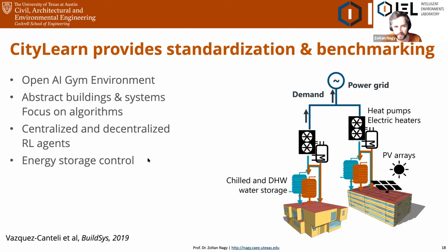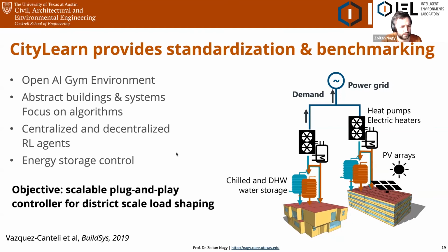All the buildings will maintain their thermal set points. We don't vary those, for two reasons. One, I don't think that's a big leverage, especially not in residential buildings. And two, this way we can guarantee that thermal comfort constraints are satisfied, so you never run into the problem of having to leave people in environments that are too warm or too cold. So there's a technical and philosophical reason to do that.